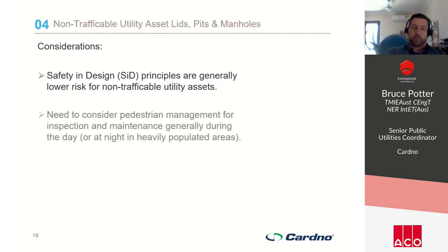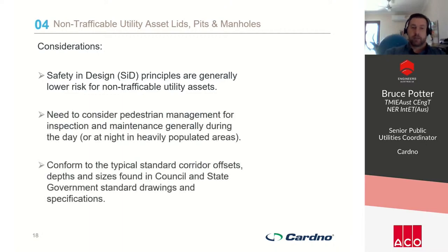Some aspects of non-trafficable lids and pits, from a safety design perspective: they're generally a lower risk because they're in pedestrian-centric areas. That still means that we don't ignore a lot of the issues. We still need to consider pedestrian management for inspection and maintenance, particularly during the day. If you've got courtyards, verges and things like that outside people's addresses, they still need to access those, and they're generally used during the day.